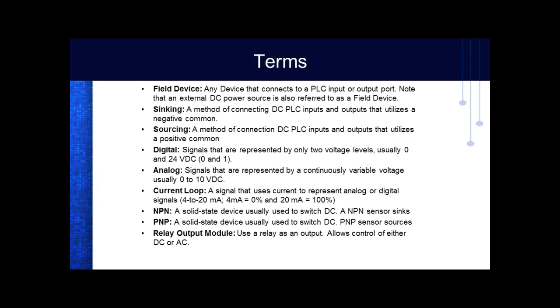So the big advantage of 20 milliamp current loops is the distances are a lot further, because what we do on a 20 milliamp current loop is a really neat system. We use what we call constant current sources, so it basically does away with resistance, as long as your output can give you the right voltage to cause the amount of current flow. These outputs measure current. If they don't have 20 milliamps, it'll raise the output voltage to get 20 milliamps. But it can only raise it so far, so you can get out of the limits.